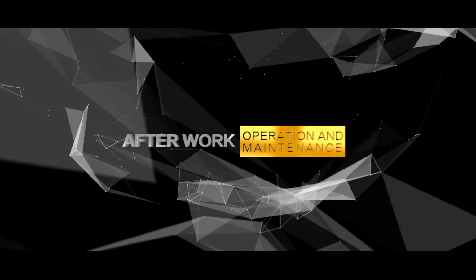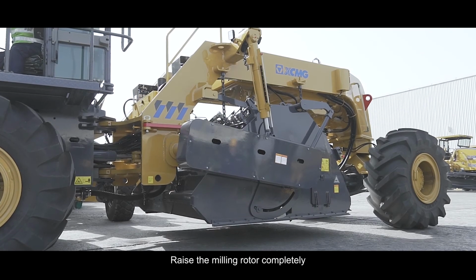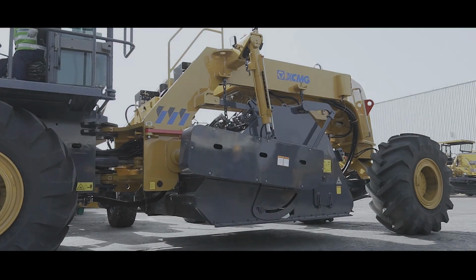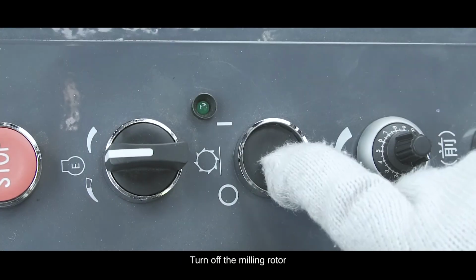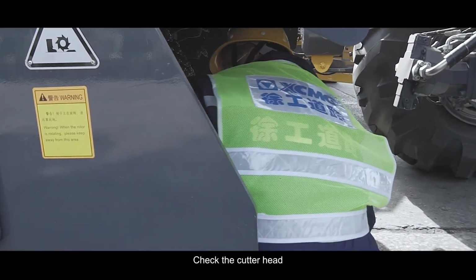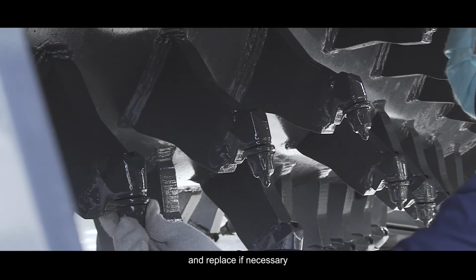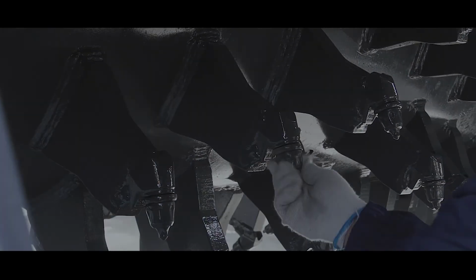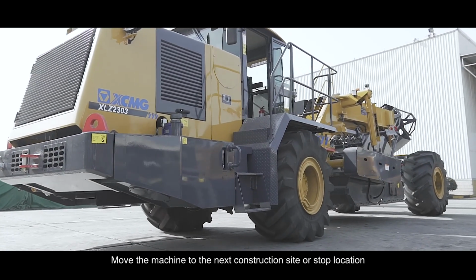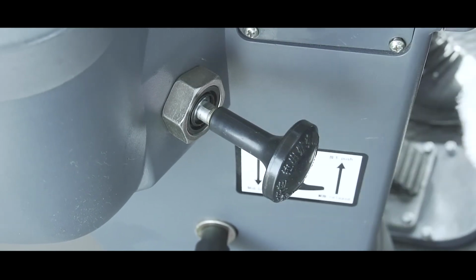After work. Raise the milling rotor completely. Turn off the milling rotor. Check the cutter head and cutter seat of the milling rotor and replace if necessary. Move the machine to the next construction site or stop location. Use the parking brake.